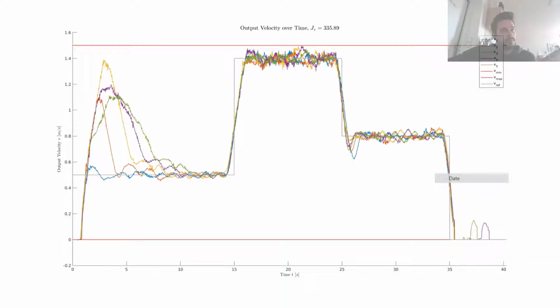So this dynamics here depends also on the vehicle dynamics, depends on the prediction horizon, of course. Maybe longer prediction horizons do not necessarily lead to faster dynamics. They may lead to slower dynamics if they are too long. You could imagine, right? And the weighting matrices are also important here.